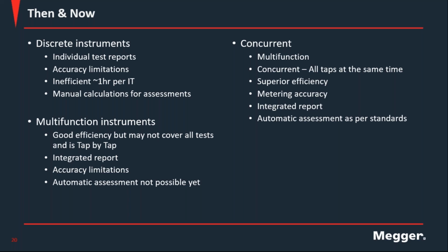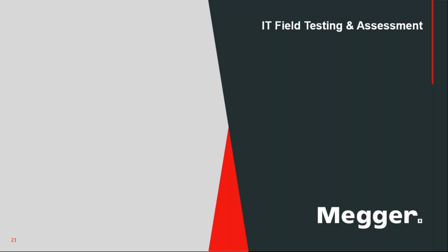And you can test not with one single instrument, you can test different types of instrument transformers. So there's not an instrument for VTs, there's not an instrument for CTs. You can get an instrument that can do all of them, and even capacitive voltage transformers that are also kind of an additional, or have their own complications. So you can test all the instrument transformers with one single instrument, and everything is in one single place, so it can perform the assessment. Let's look into the results.